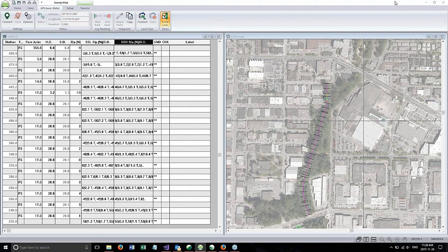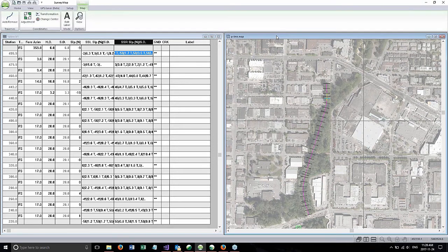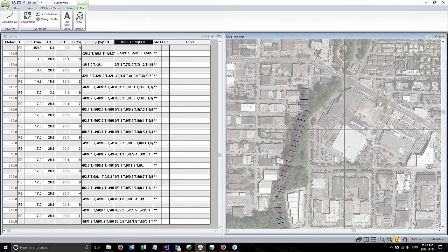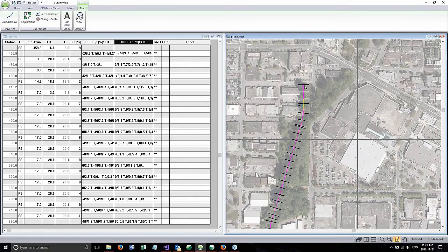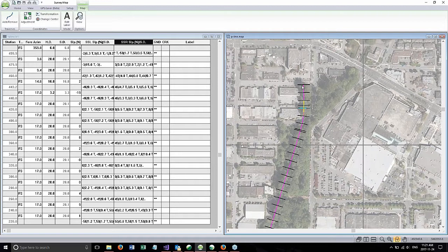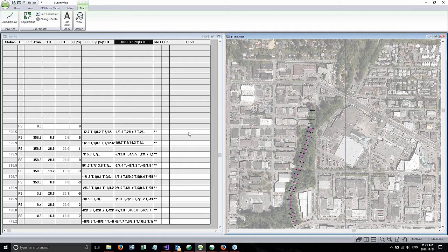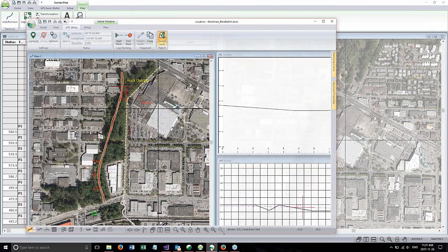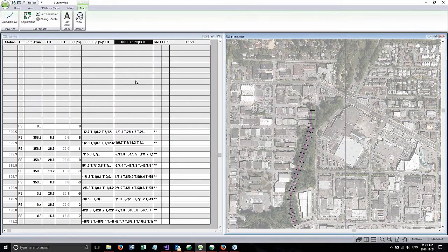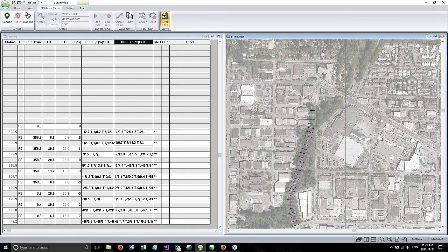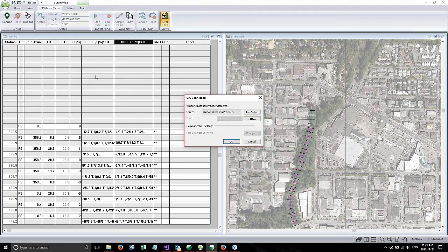So again, same area that I have for the office here. I've artificially created a P-line traverse that runs near the office here. And what I can do is I could set the start station for this traverse. I could set it absolute, or I could come out here and let's turn on the GPS here as well. Just make sure. Okay. So GPS, same thing. Just connect. Exactly the same stuff is in location. So there's my position.